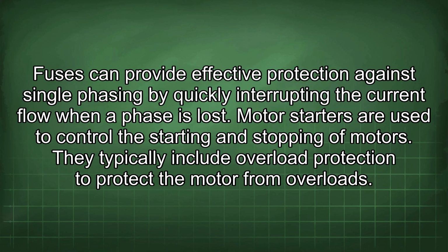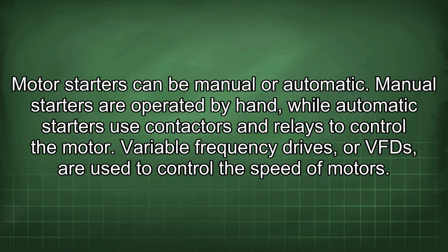Motor starters are used to control the starting and stopping of motors. They typically include overload protection to protect the motor from overloads. Motor starters can be manual or automatic. Manual starters are operated by hand, while automatic starters use contactors and relays to control the motor.